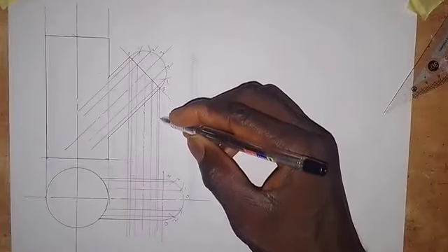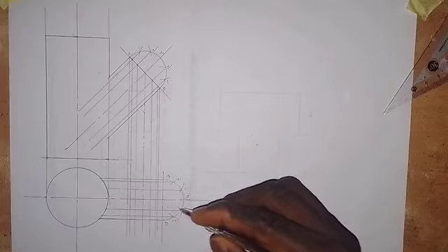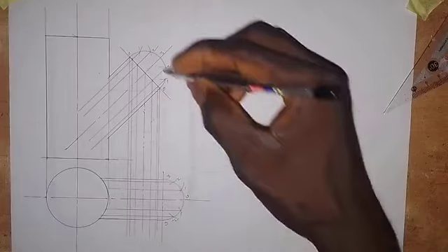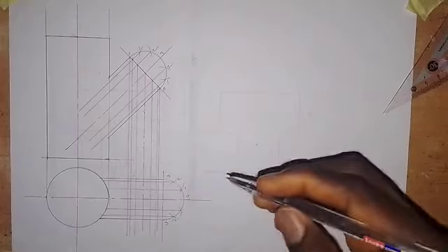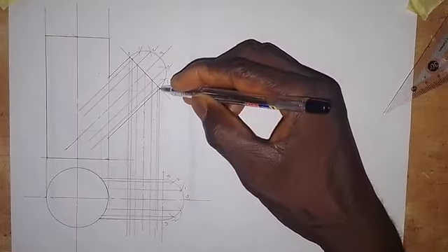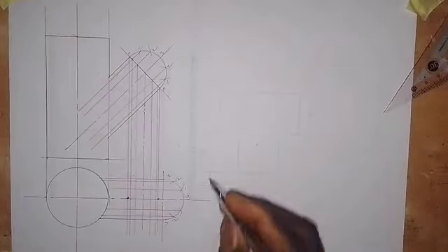Okay, so the purpose of drawing vertical lines here that intersect this horizontal line is for us to bring out that shape, and let's look at how it goes. Now this is line 0, and it intersects this line 0 at this point. That's why I say you have to number differently. If you number them as you numbered here, you'll not be able to work this out. So you must number differently, so pay attention to that. So this vertical line 0 intersects horizontal line 0 at this point. So we take note of this point, and we also have 0 on this side, so we also take note of this point here.